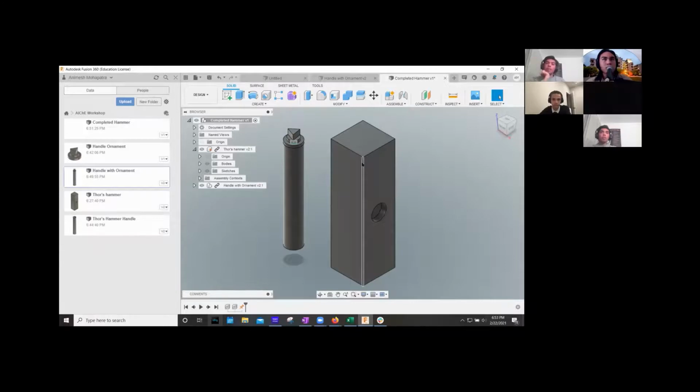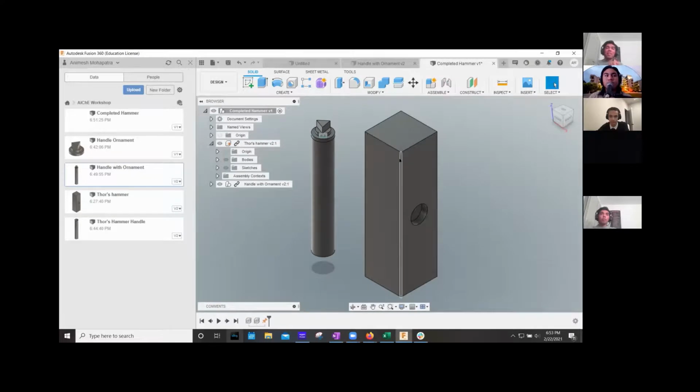This is particularly important if you're making a really big assembly, because if you just have random pieces moving, it can get very confusing. You might think, oh, my piece is at the origin, but then suddenly it's not. It's at like negative 550x, negative 20y, and negative 80z or something. So yeah, grounding is a very helpful thing to have.